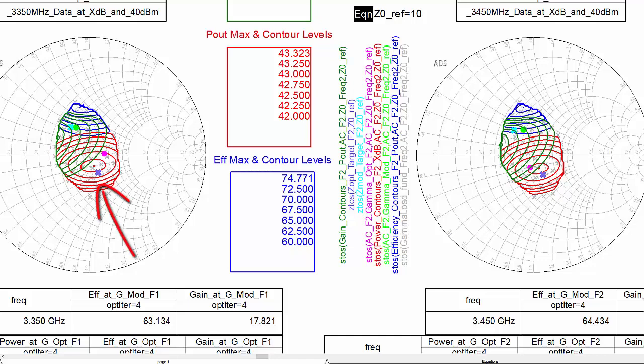The purple X's show target impedances to be generated by the output matching network when the peaking amplifier is on. These are the high power impedances, sometimes referred to as Z-opt. The pink dots are the impedances generated by the matching network after optimization and are close to the target values.